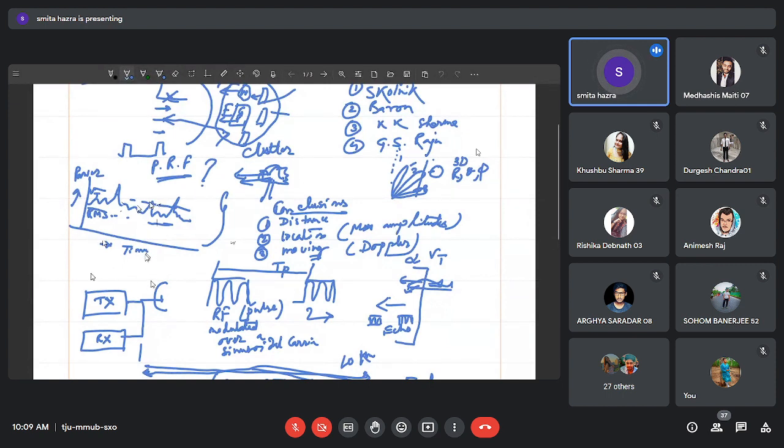Sometimes in the same resolution cell, a very weak signal from a newly appearing object and the disturbance of clutter are both there. So there we need a larger number of resolution cells, so that we can become distinctive about the presence of the new object with respect to the clutter disturbances.